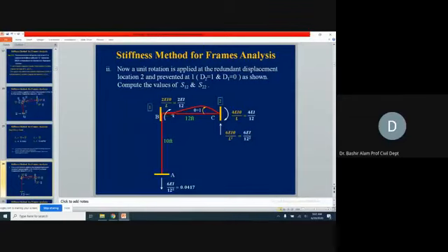Here we are not allowing any rotation now. If we draw a tangent here, so here you see to the tangent, this is making a clockwise now, theta is equal to 1 now. This is becoming our now near end, and this is the far end now. So at near end, the moment generated will be 4EI theta over L, which is 4EI over 12 in this case.